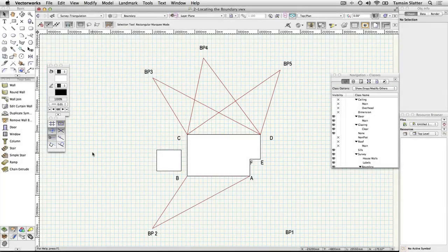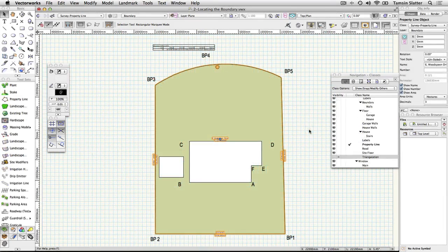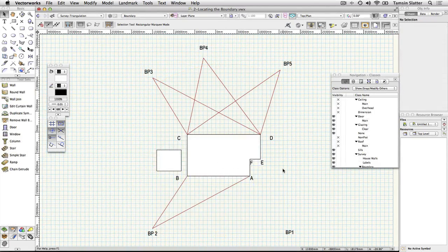Drawing up the site. We'll use example files to look at how to locate points on site and to draw simple buildings. The sample file we'll use contains two simple polylines representing the footprint of a building. Later you'll turn these into a building. There are also some triangles that represent triangulation points to the boundary. In this exercise you'll learn how to use the triangle tool to locate the final boundary point.